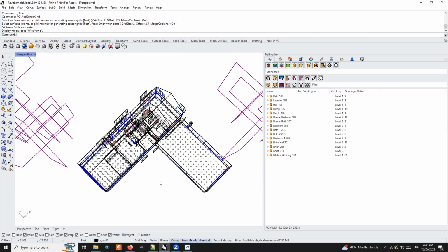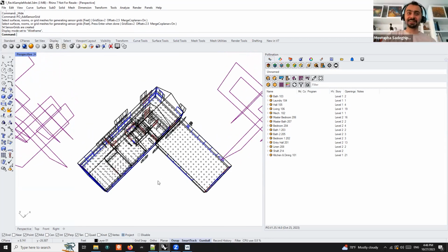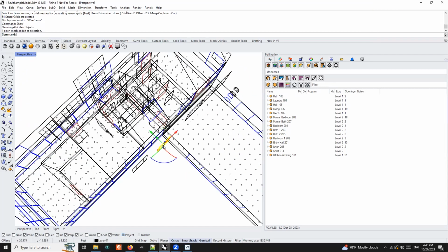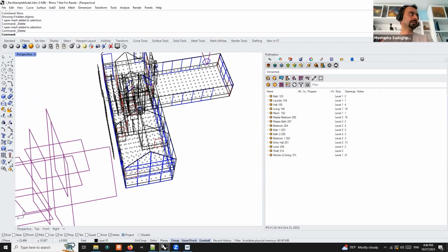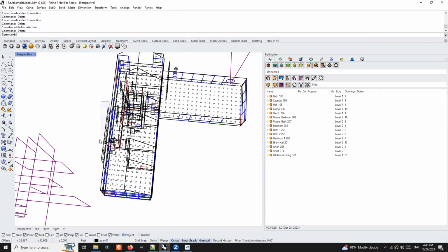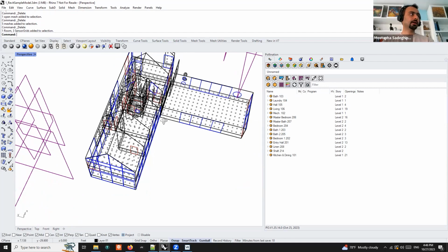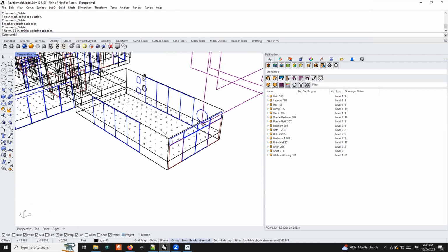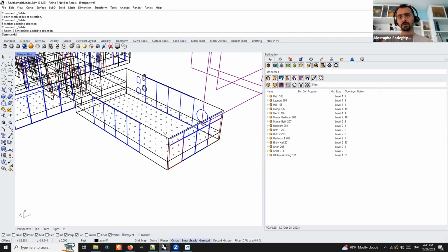Yes, it is. Does it make sense? Yeah. Otherwise, you don't need to hide the rooms not to select them, of course, in Rhino. You can just deselect them. It's a good thing. Yes, I didn't know that for LEED purposes, I needed to have it room by room. Yes, again, for LEED option 1, right? Yes. For option 2, you don't need to, because for LEED option 1, when we want to run that annual direct sunlight logic, we need to know which apertures are related to that. That's why. Good question. No problem.